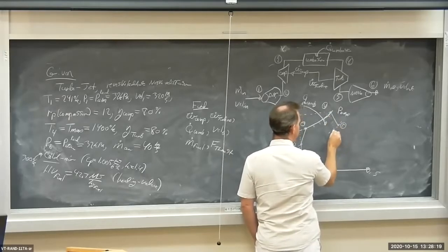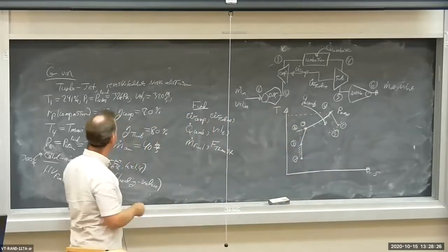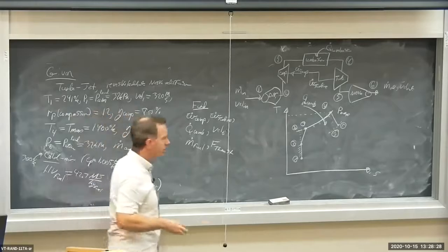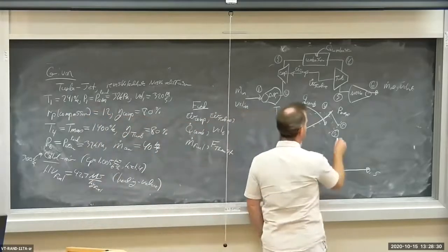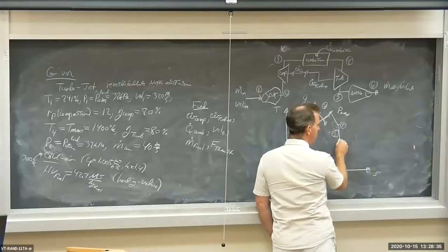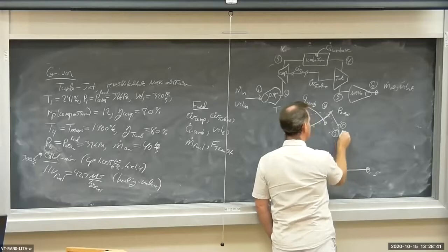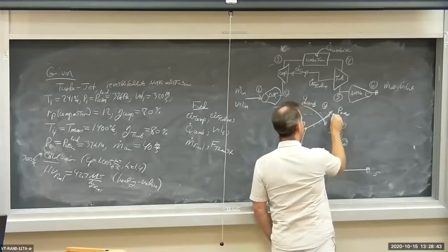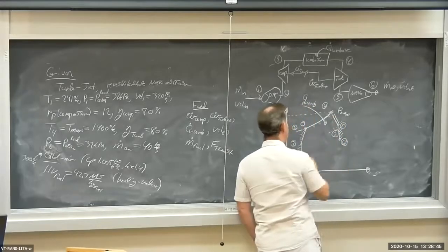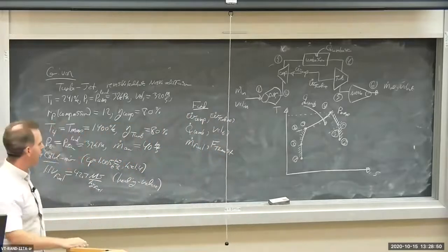Of course, here's the isentropic process, here's 5 sub s. And then we have reversible adiabatic, therefore isentropic, expansion in the nozzle. So the nozzle converts enthalpy into kinetic energy, and we have an increased outlet flow velocity. So this is state 6, okay? And these are all adiabatic except the combustor. So there's the TS diagram right there.